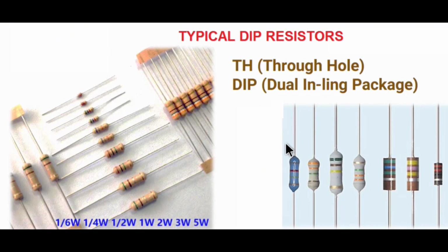Another point is that ordinary resistors have different powers, and in addition to their ohm value they are identified based on their power. For example, they say a resistance of 100 ohms at 1/4 of a watt. A resistance of 100 ohms is, for example, 1 watt, for example, 5 watts, 10 watts.